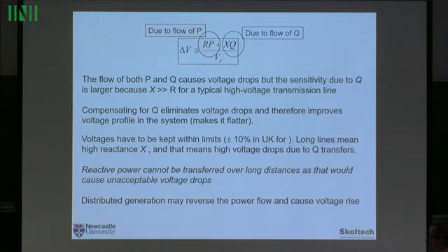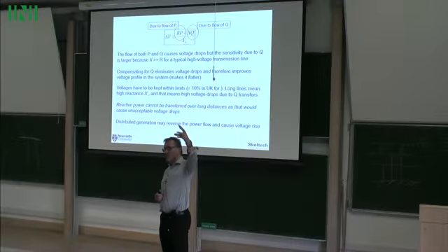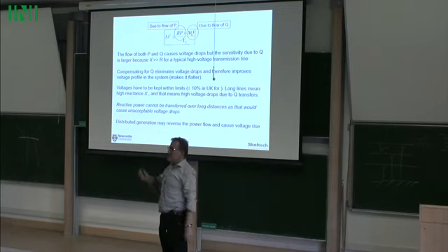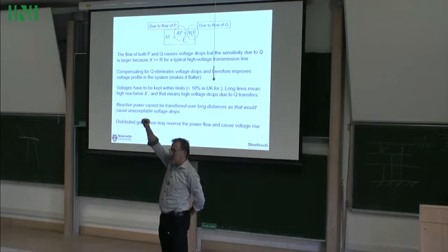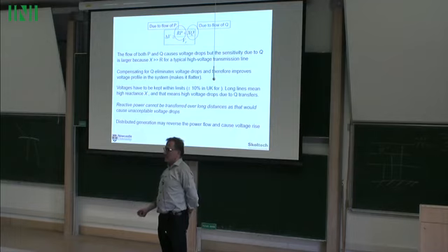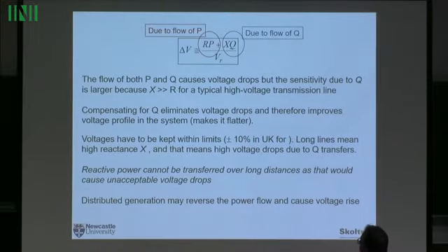And the last point is about wind, generally speaking. So as I mentioned, traditionally power, both real and reactive, would flow from generators down to the loads. It means reactive power on the distribution network would flow from the top down. That means that the voltage will be high at the substation at the beginning of the feeder and be lower at the end of the feeder. What happens when you put the wind farm at the end of it? When you put a wind farm at the end of it, you change that: P would be big, but will be negative. It will flow in the opposite direction.